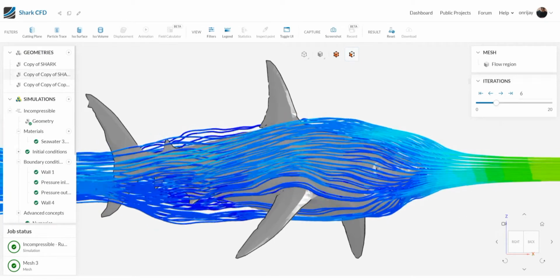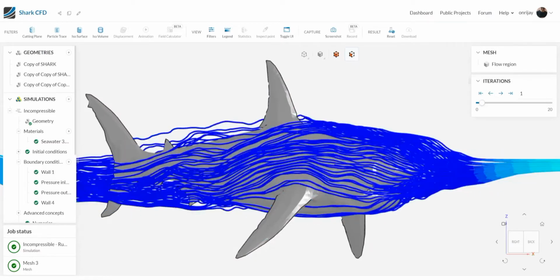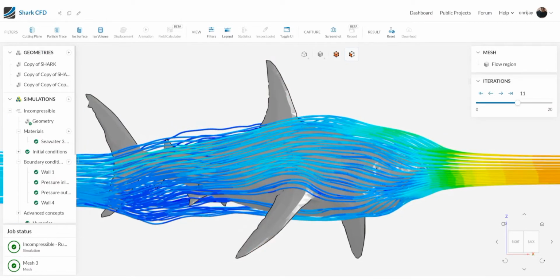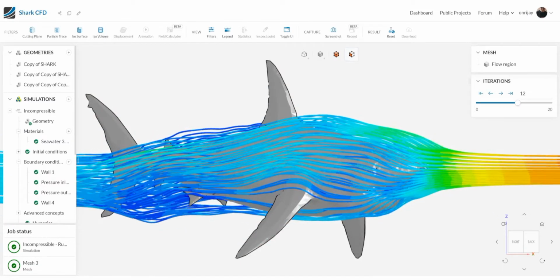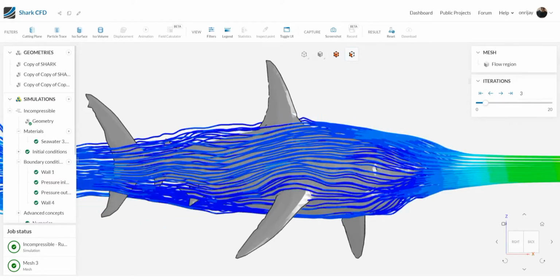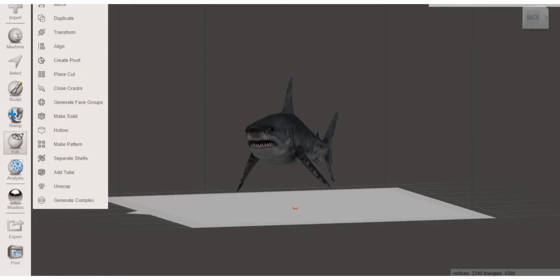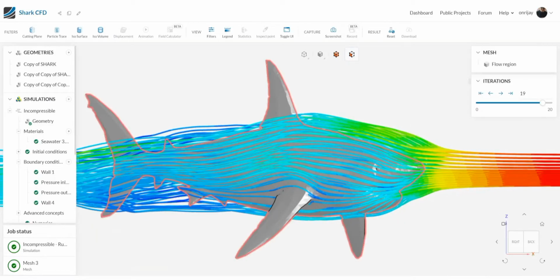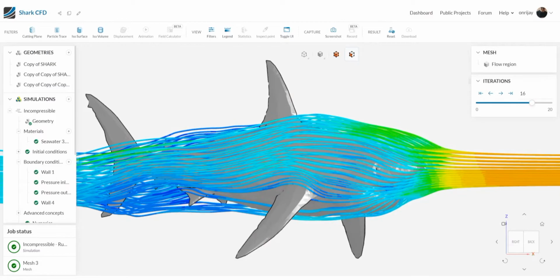And basically, we have to get to this point where we have a fluid flow around a 3D object like this. There are a series of steps that one has to take. One, of course, is double checking for the meshes. So in this case, there are meshes. We are aware of those meshes, and you can also double check with the Autodesk Fusion 360, make sure the meshes are present. That's it.